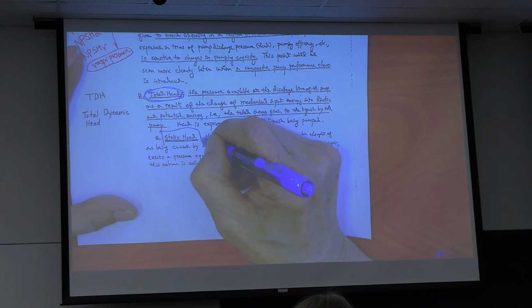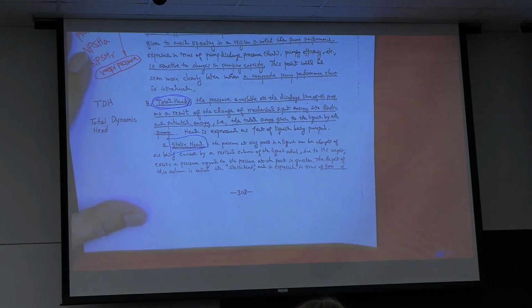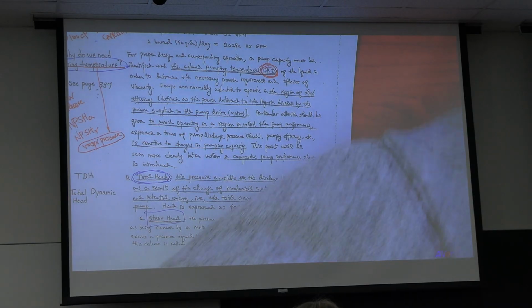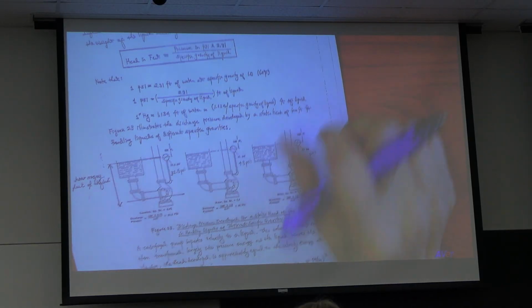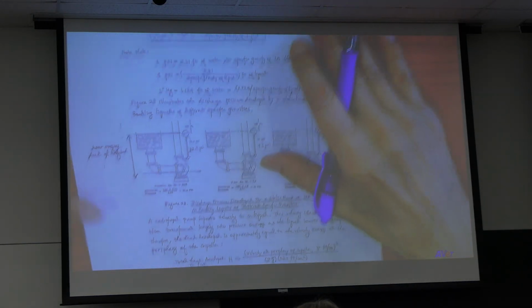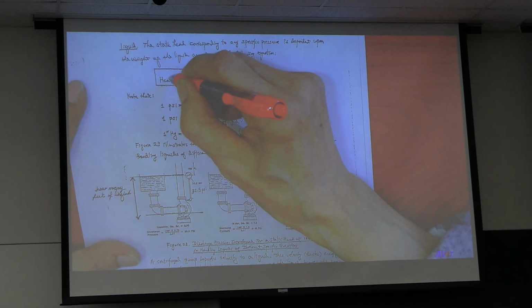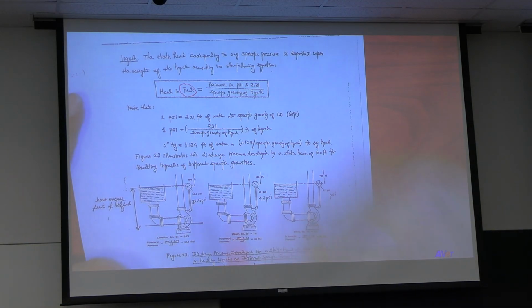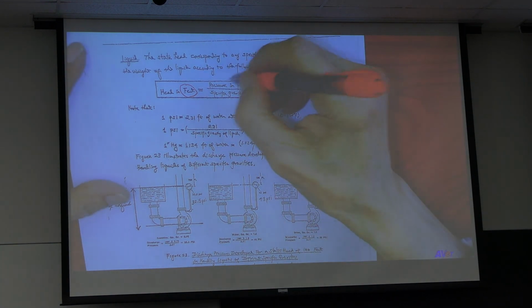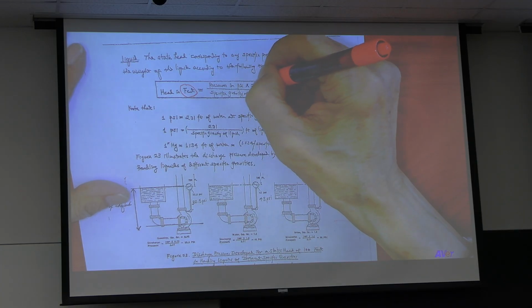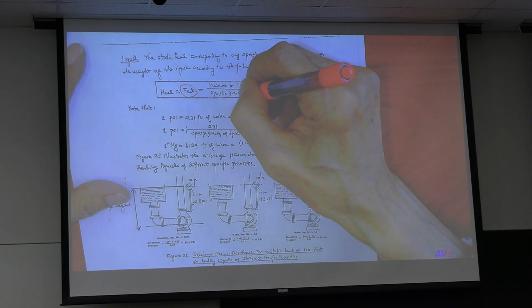First, static head. Look at page 310. Head in feet: the pressure in PSI times 2.31 divided by specific gravity.